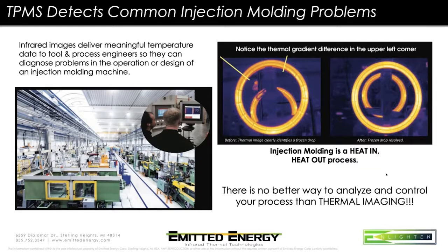But this was a stack mold that had 4 drops onto it, and these people would start up and start molding their product, and they couldn't understand why, after an hour down the line when they let their parts cool, they had this warping going on. It's because one of their nozzles got clogged up, and that was the one up on the top on the left-hand side there. And so we had started to run this, and that second shot said, "You got a clogged nozzle." They said, "No, we don't.